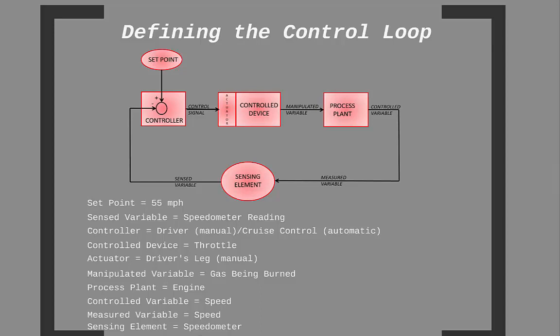and then it sends a command, termed the control signal, to the control device. The actuator and/or control device take that command and do something about it. They are the muscles that adjust something in the system to change how the system operates. It should be clear that this is a continuous loop. There will be a constant comparison between the sense variable and set point. Adjustments being made will in turn affect the controlled variable. Such changes would be sensed by the sensor. That information is relayed back to the controller, and the process starts all over again.